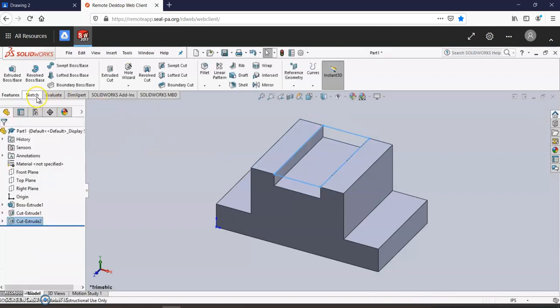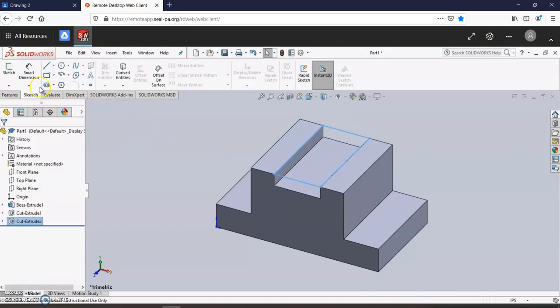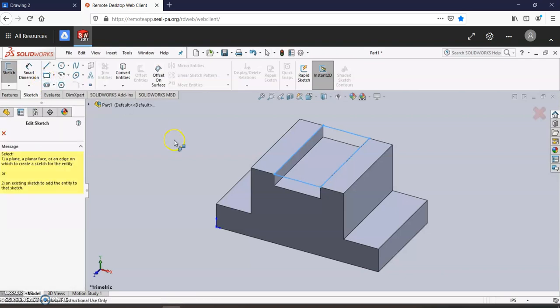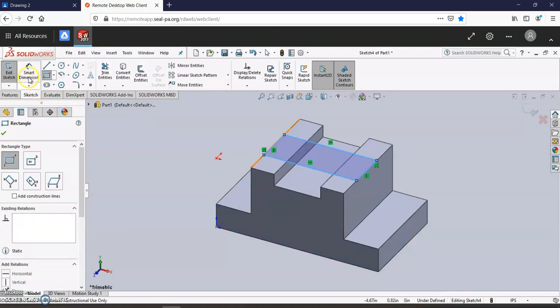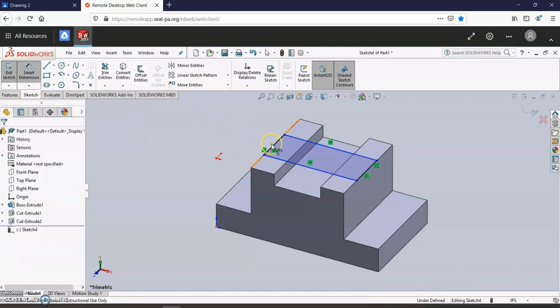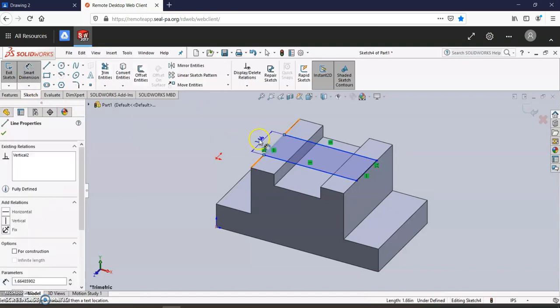Now, next step, Sketch. Right back to the first step, Sketch. Choose the shape. This plane and this plane, it's the same plane, so it doesn't matter which one you click. Make sure you don't start or end on your midpoint, so just find it and move away. It's in here somewhere. There it is. So just move away. And it's the same as the other one, basically the same dimensions, just indexed 90 degrees.